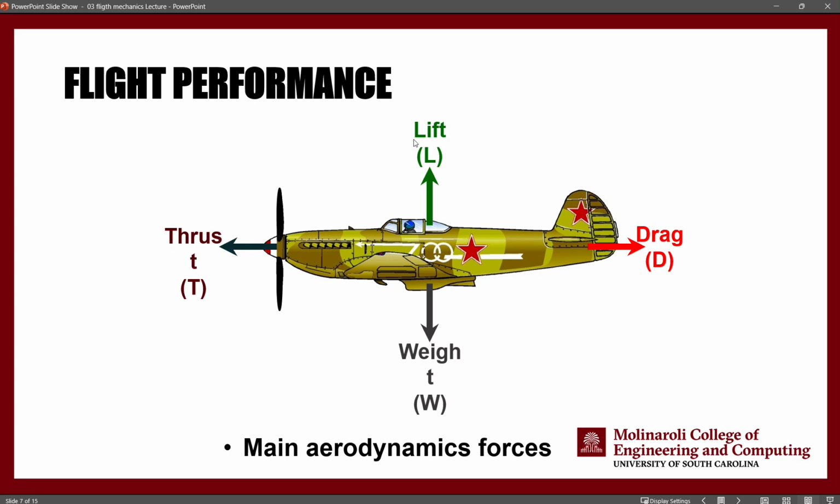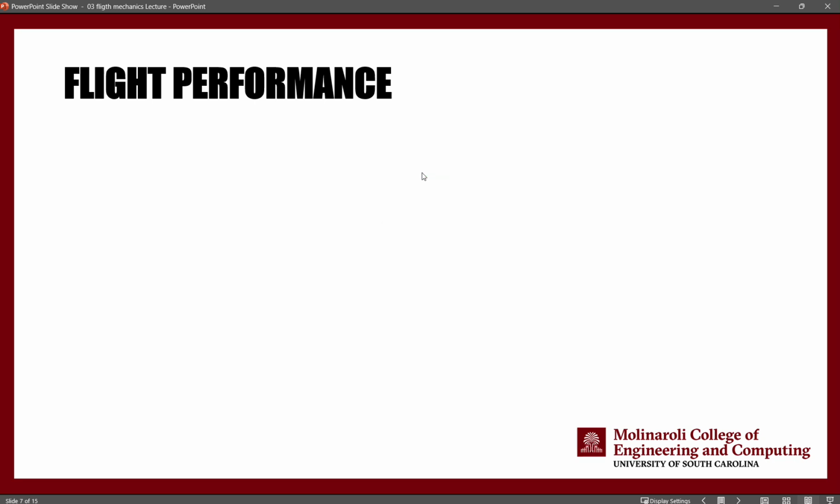So the aerodynamic forces that are important for us are lift and drag. And using the flight simulator, you can actually export the lift and drag data during any type of flight that you are performing using the flight simulator. The idea is you need to record this data, lift and drag data specifically, and the angle of attack. We will talk about angle of attack in the next slide, do some sort of aerodynamic analysis, and present that analysis in your lab reports.